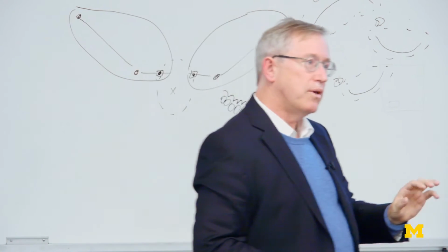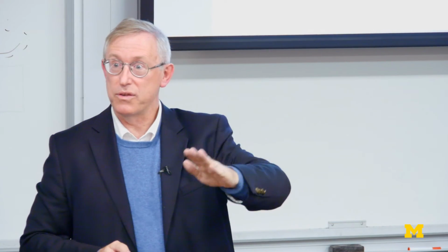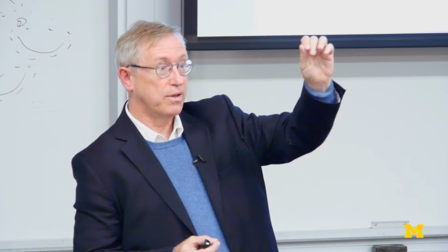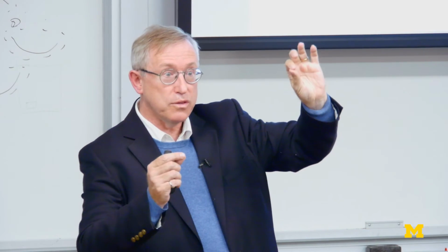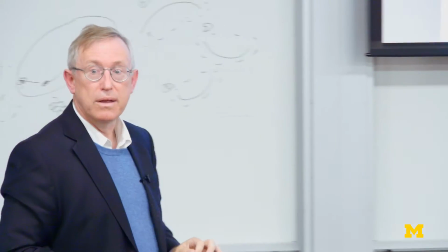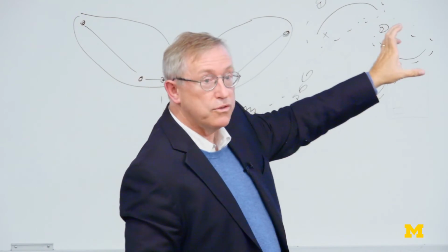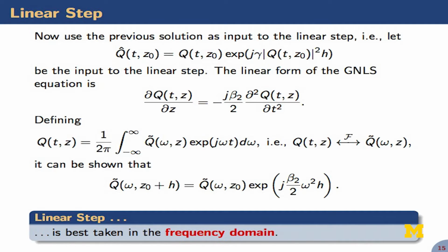It's a type of temporal all-pass operation in a sense, like the dual of an all-pass filter in signal processing. This is in time here, right? So it's got this unit gain. It's not redistributing the amplitudes in time. It's changing the phase. That's what the nonlinearity is doing. This is the so-called self-phase modulation that's occurring in the fiber.